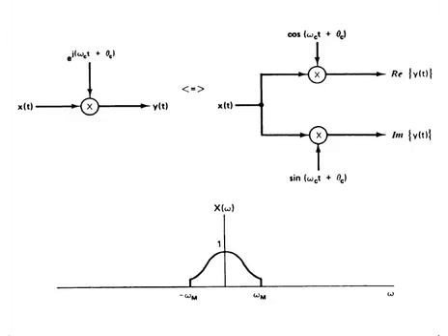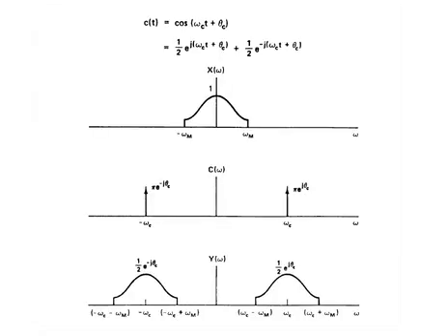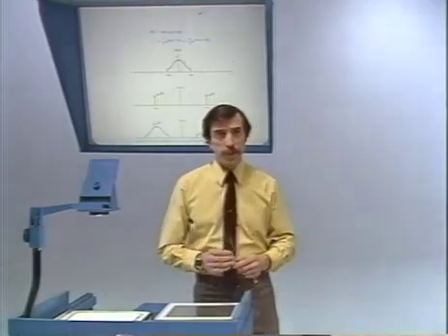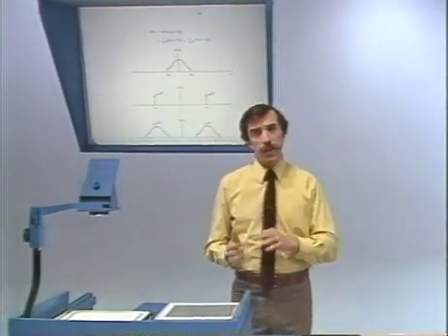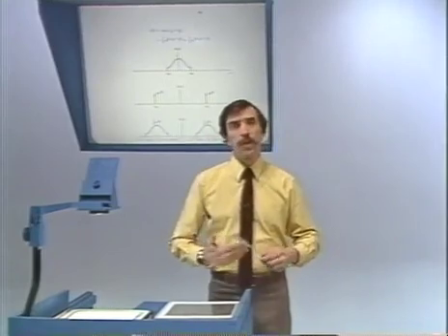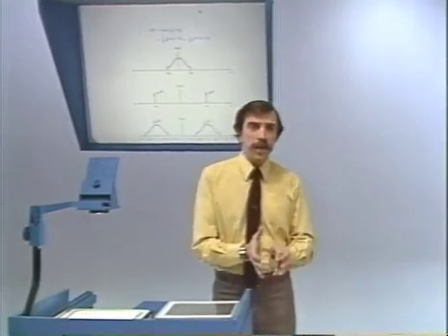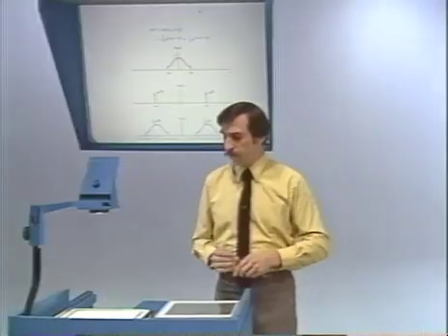Okay, well, sinusoidal modulation, in other words, modulation using only a sinusoidal carrier, very often is used in its own right, not only for generating a complex exponential carrier, but as a carrier by itself. Let's look at the consequences of modulation with a sinusoidal carrier, and in particular work through again what the spectra are and how we get the original signal back again.